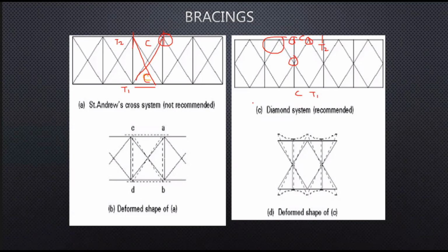So in the case of integrative design, you need to put the members in such a way where the effective lengths on the compressions can be reduced by introducing something like a secondary brace, a delta brace, and like that. So you are free, you can pitch and play with the provision of the braces.